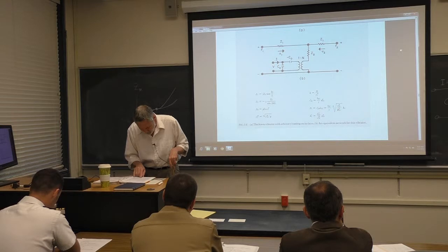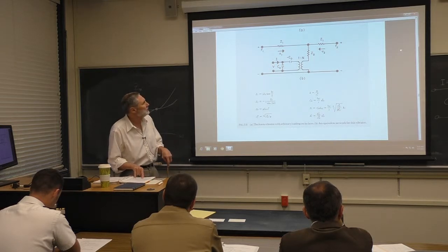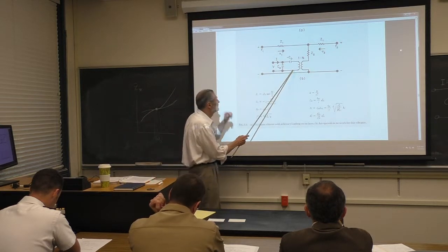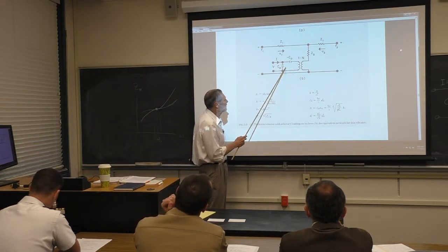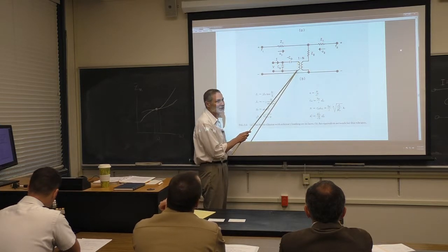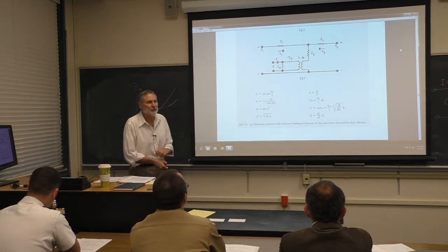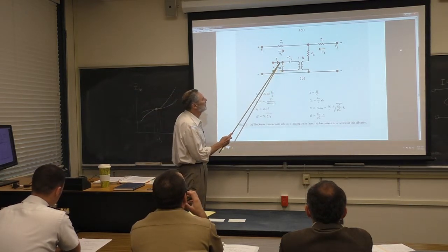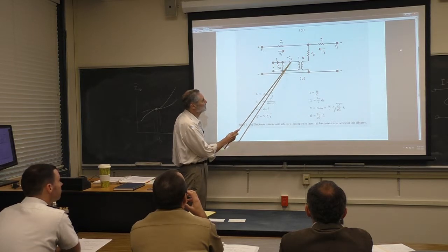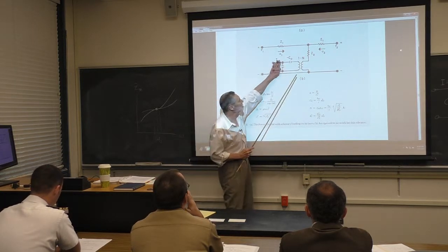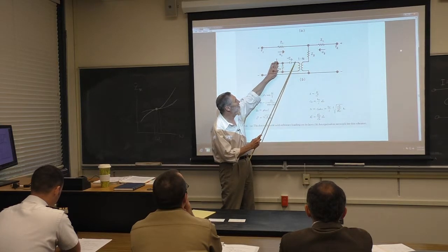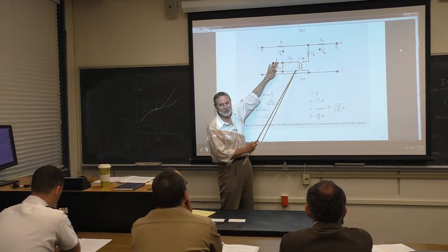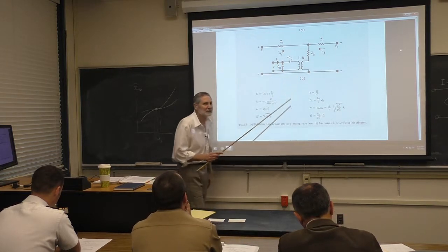Okay. So what's I prime is not necessarily 0, but look at this. What's the voltage drop across here? Kirchhoff's loop rule immediately tells us. There's a V across here, there's a capacitor in the way. Just focus your attention on this. What's the voltage drop across here compared to the voltage drop? They cancel. So there can be no voltage across here in this case.